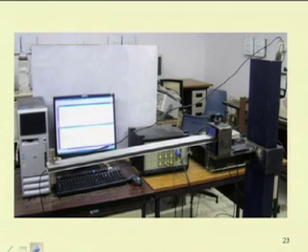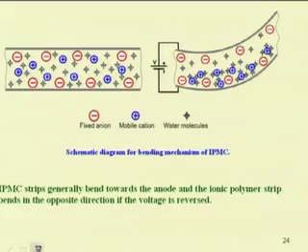This is one experimental setup, in which by putting the accelerometer, we are finding the natural frequency of the system. This is a cantilever beam, the cantilever sandwich beam. Here the accelerometer is placed and it is fixed at this end. So, when it is subjected to an excitation, then one can find its response.